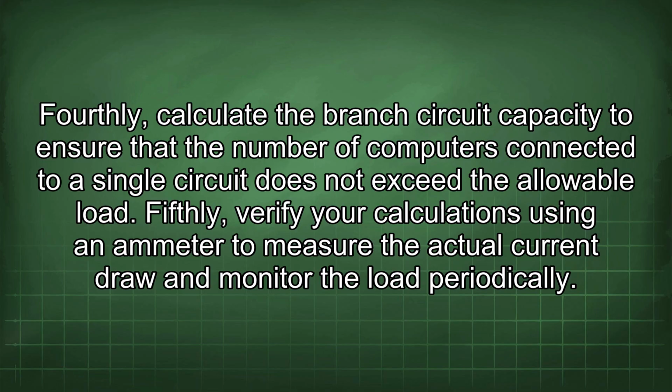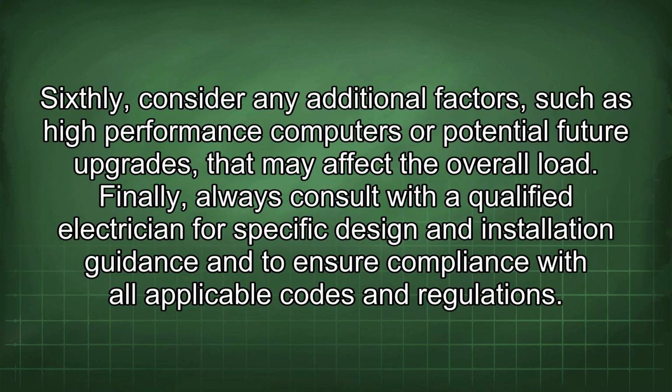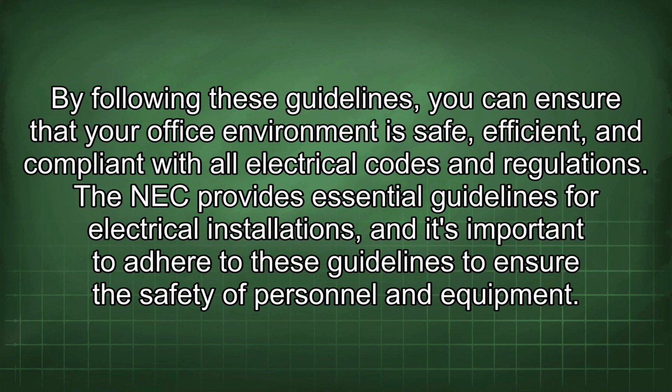Fourthly, calculate the branch circuit capacity to ensure that the number of computers connected to a single circuit does not exceed the allowable load. Fifthly, verify your calculations using an ammeter to measure the actual current draw and monitor the load periodically. Sixthly, consider any additional factors, such as high-performance computers or potential future upgrades, that may affect the overall load. Finally, always consult with a qualified electrician for specific design and installation guidance and to ensure compliance with all applicable codes and regulations. By following these guidelines, you can ensure that your office environment is safe, efficient, and compliant with all electrical codes and regulations.